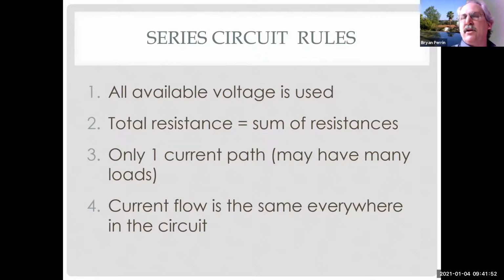So I can take it totally to the next level. My injectors use one wire for the power, and on my 6-cylinder they use 6 different wires for the grounds of 6 separate circuits. I can measure each of them individually to measure the current, or I could clamp on and measure the current on the positive wire at the fuse or whatever feeds all the injectors, and measure them all with one connection. Since they should all have the same resistance, they should all flow the same current, right? So if I have one that flows a much different current, I've just found my problem without taking anything apart.